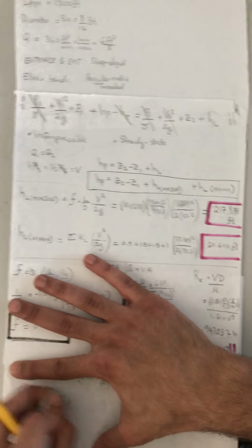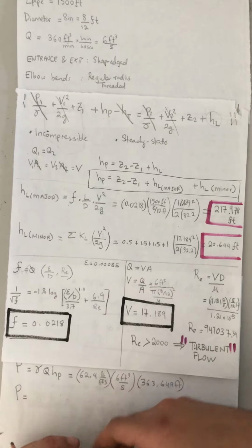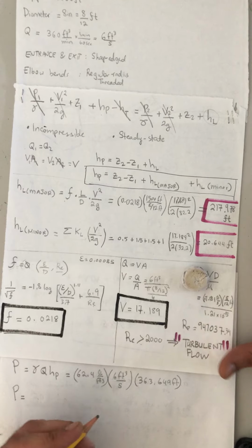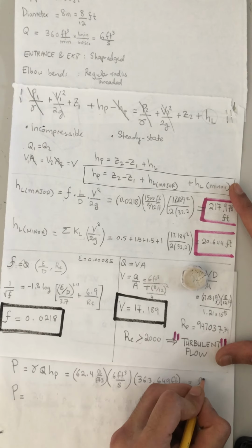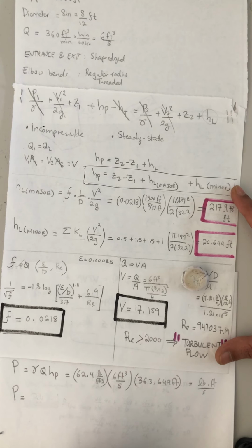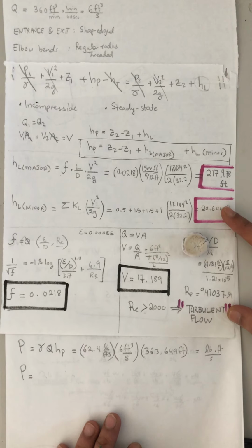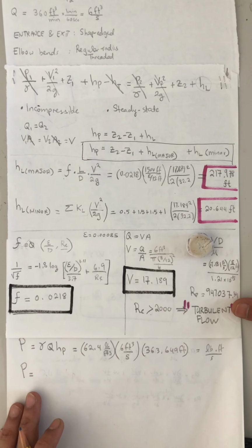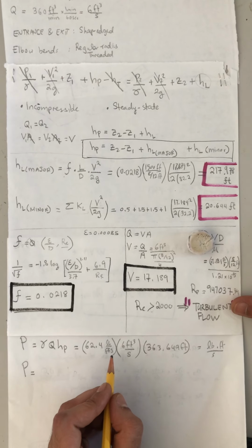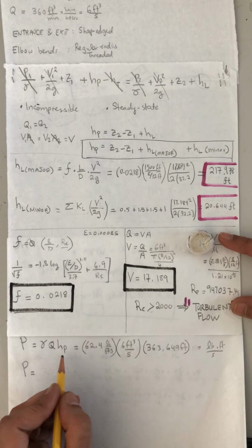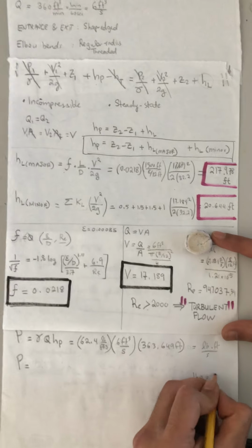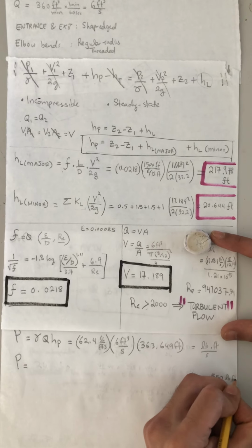And it is important to note that the units that we are left with are lb-feet per second. The traditional units for pump performance are horsepower, so we would like to convert our value to horsepower. We know 1 horsepower equals 550 lb-feet per second.